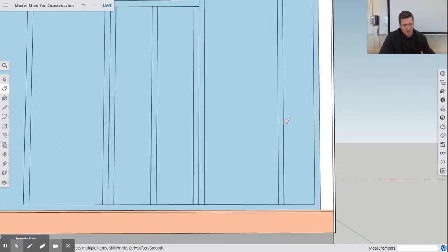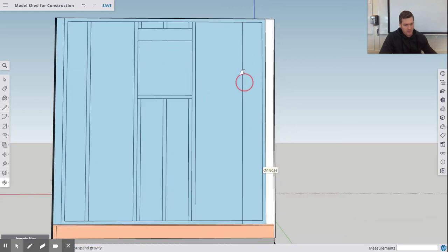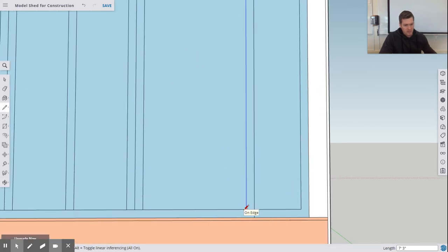I'm going to come back here and modify these. Once I erase those, I'm going to click my draw command. I'm going to go with 13.75 again, click that and go straight up to the top there. And from that over 1.5. And from that straight back down to there. All right. Remember, all dimensions I'm typing in are coming up down there. So if you don't know where the dimension's at, always take a look down here in the corner and it'll show you where the dimensions should be at.